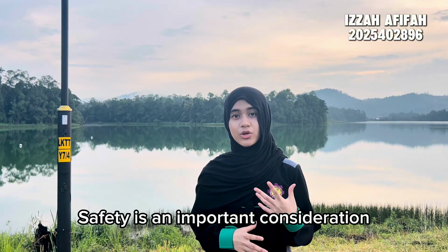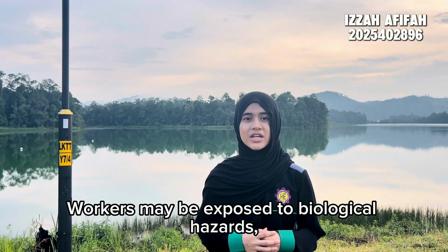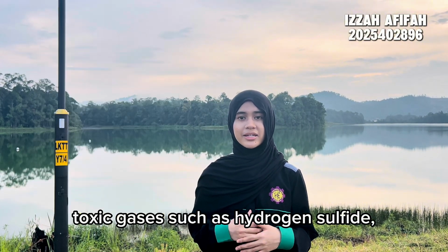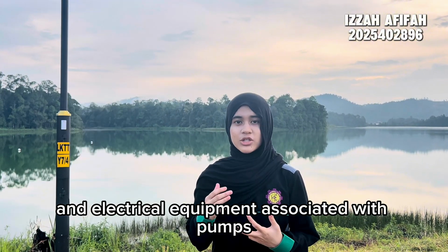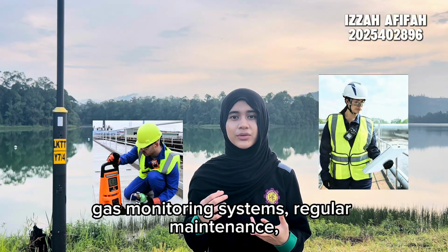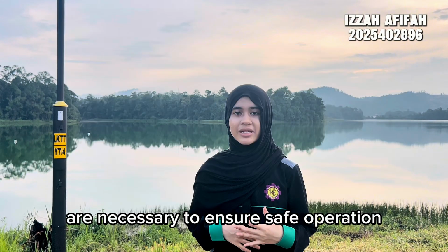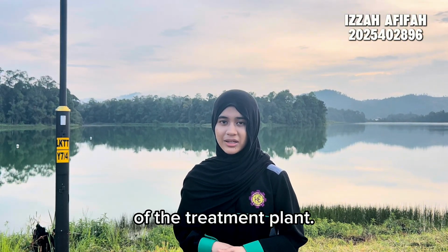Safety is an important consideration in wastewater treatment facilities. Workers may be exposed to biological hazards, toxic gases such as hydrogen sulfide, and electrical equipment associated with pumps and aeration systems. Appropriate personal protective equipment, gas monitoring systems, regular maintenance, and operator training are necessary to ensure safe operation of the treatment plant.